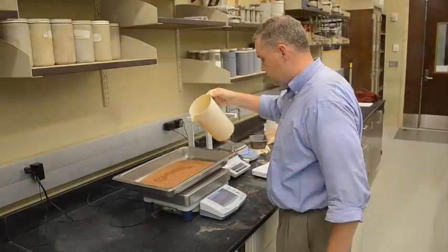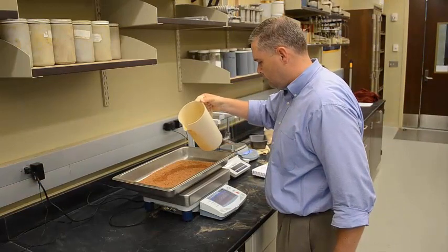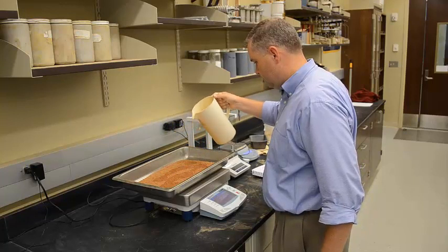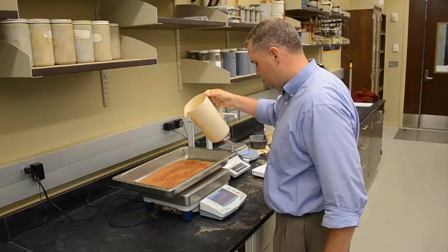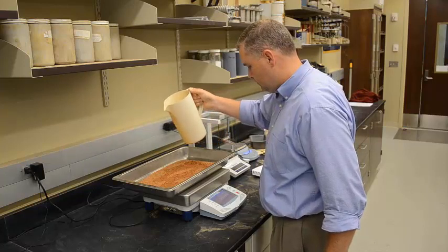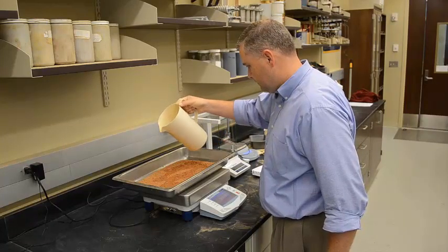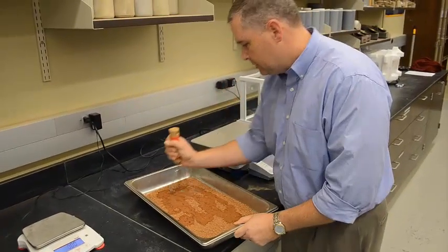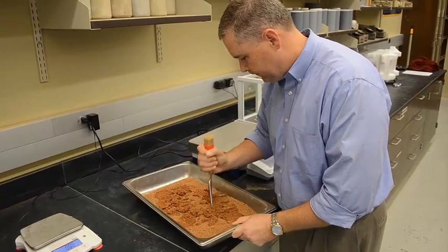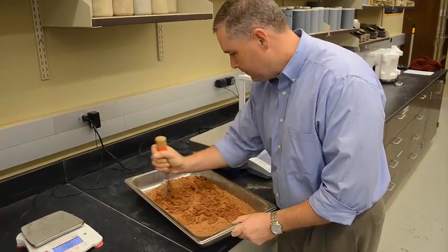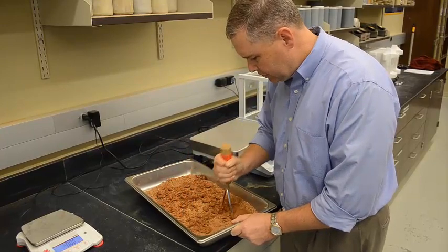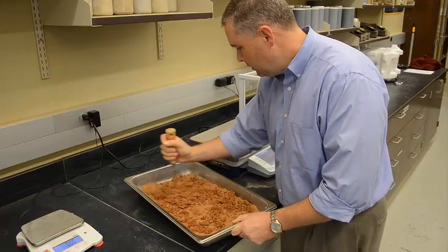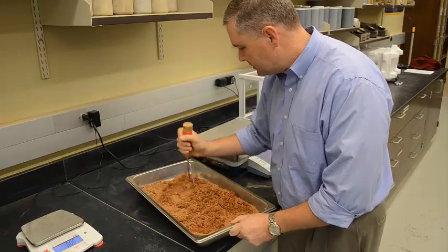Okay, so what you want to do is collect about 5.5 pounds of material, and then you need to know the exact weight of that material, and then you add the percentage of water that you need to get the material up to about 4 or 5% below the optimum moisture content. So if you were to have, say, 3 pounds of material there, or you can do it in grams, right? If you have it in grams, you would add the appropriate amount of percentage of water by weight to this, and that's what I've done here.